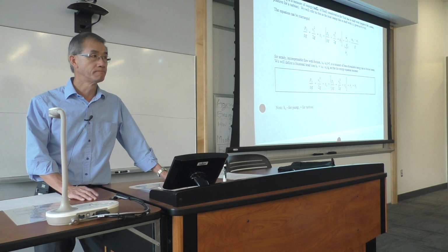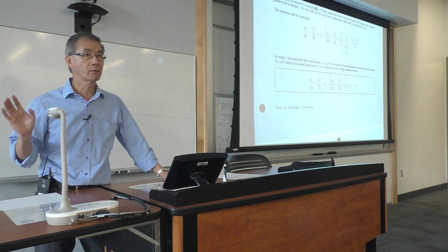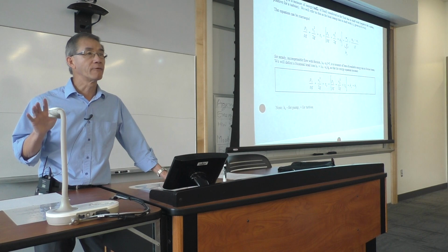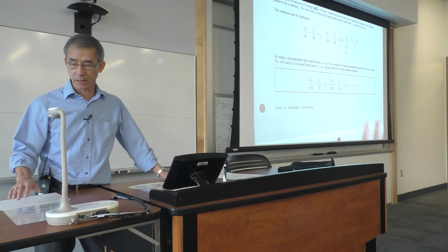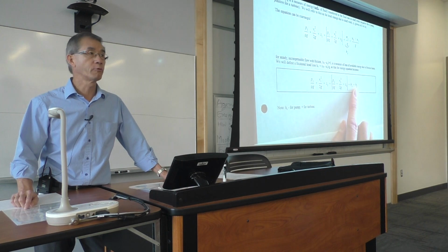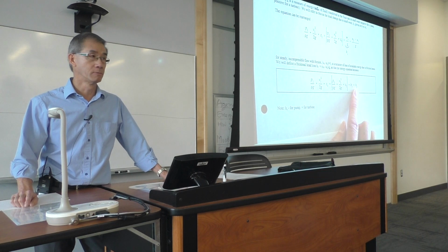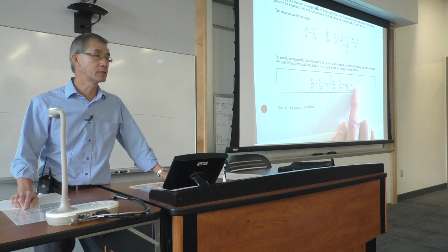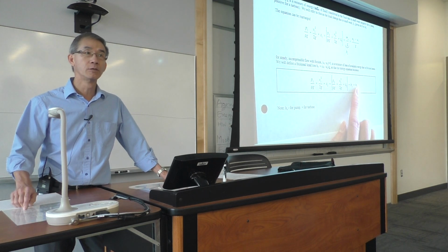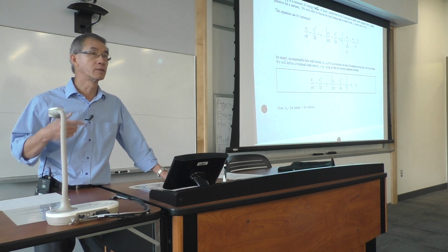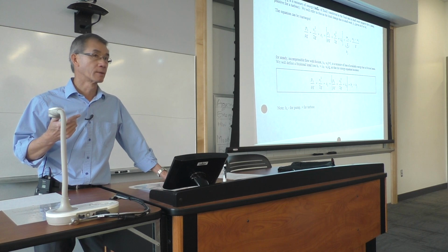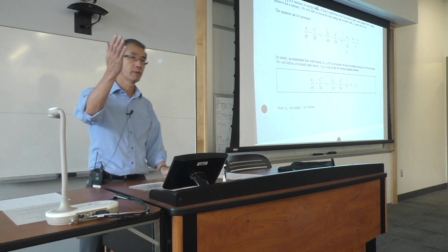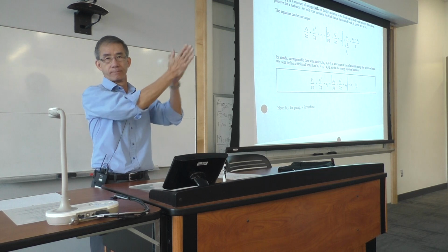Cv delta T. So here's how the second law, entropy, availability all come into this discussion now. This so-called frictional head loss, friction losses, is nothing but a representation of the increase in internal energy, U2 being higher than U1, due to friction. How does that happen? Take your hand and rub it.